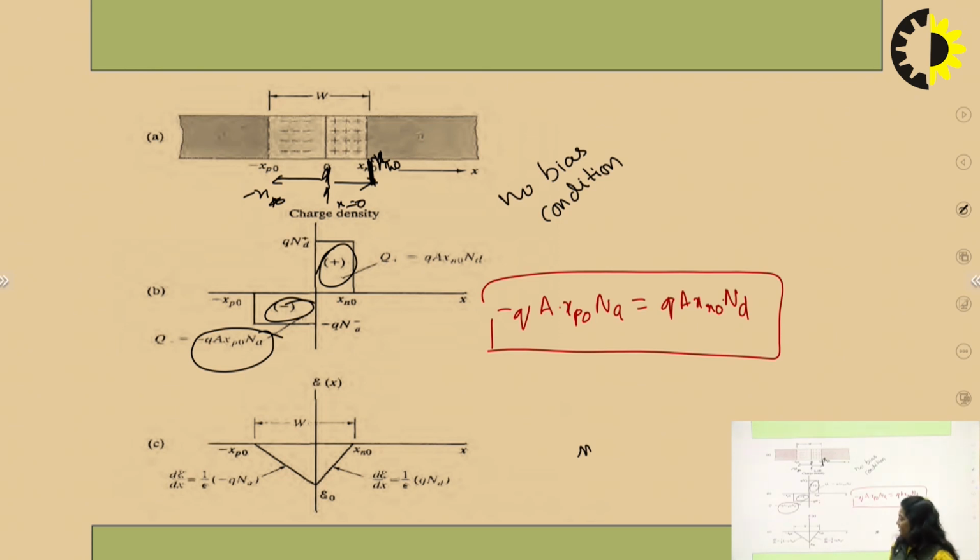And if we see the electric field, because some charge is present, obviously there is an electric field also present. The electric field is maximum, because the potential increases from this side to this side. This is the graph of the contact potential. At the junction the transition is maximum, since Ex is minus dVx upon dx.